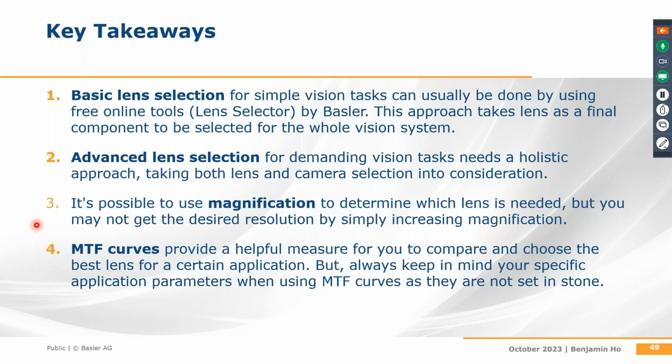Third, it is possible to use magnification to determine which lens is needed, but you may not get the desired resolution by simply increasing the magnification. Fourth, MTF curves provide a useful measure for you to compare and choose the best lens for a certain application. But always keep in mind your specific application parameters when using MTF curves, as they are not set in stone. With these four points in mind, I would like to end the webinar today.